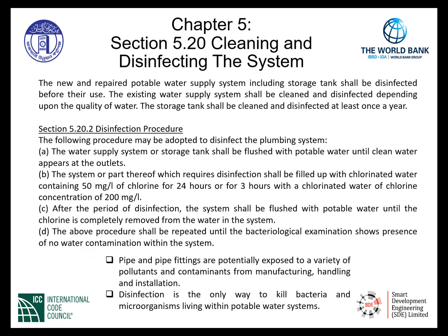Section 5.20, cleaning and disinfecting the system. The new and repaired potable water system, including the storage tank, shall be disinfected before their use. The existing water supply system shall be cleaned and disinfected depending upon the quality of water. The storage tank shall be cleaned and disinfected at least once a year. Section 5.20.2 gives us the procedures.